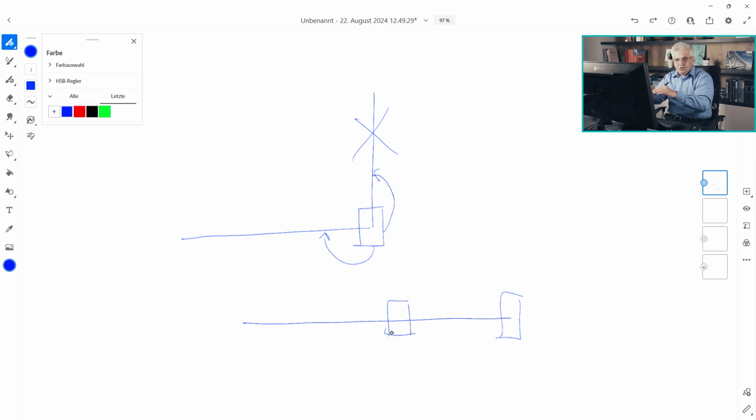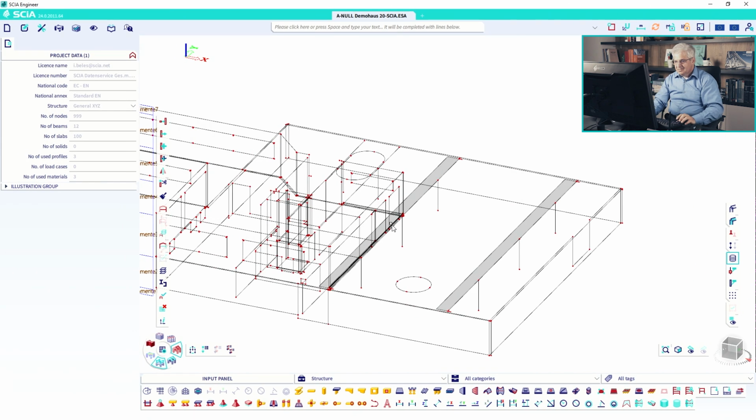Then they are connected to the plates and not to the walls, because if they are connected to the walls, they will also get rotation, and then you see it in a horizontal way. So it's not very nice, but the engineer has to do something, and if you leave the decision, then it's doing something. So you have to select that it should go to the plate.